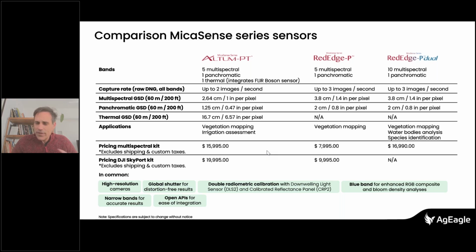But you need to get into the settings, and I would recommend 1.5 images per second, not much more than that, right? So if you're flying with a fixed wing drone, you need to fly high enough. High enough means 120 meters should be okay, not much lower than that. Else the overlap is not good enough. And as I explained earlier, we need very good overlap to have a consistent multispectral map.